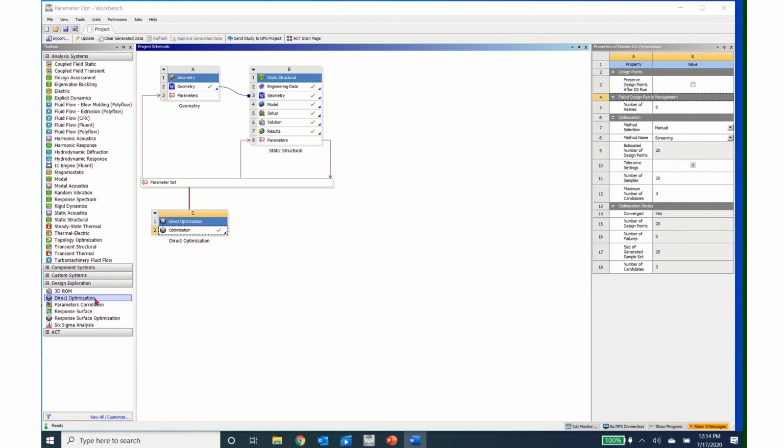In this tool, you can have Ansys generate a list of cases, or you can manually type in the parameters and then have Ansys solve for each set of parameters. In this type of analysis, it's not clear how one parameter affects another. It is also not clear what parameters are really the drivers for the optimization. However, it can provide pretty good results with relatively vague inputs.